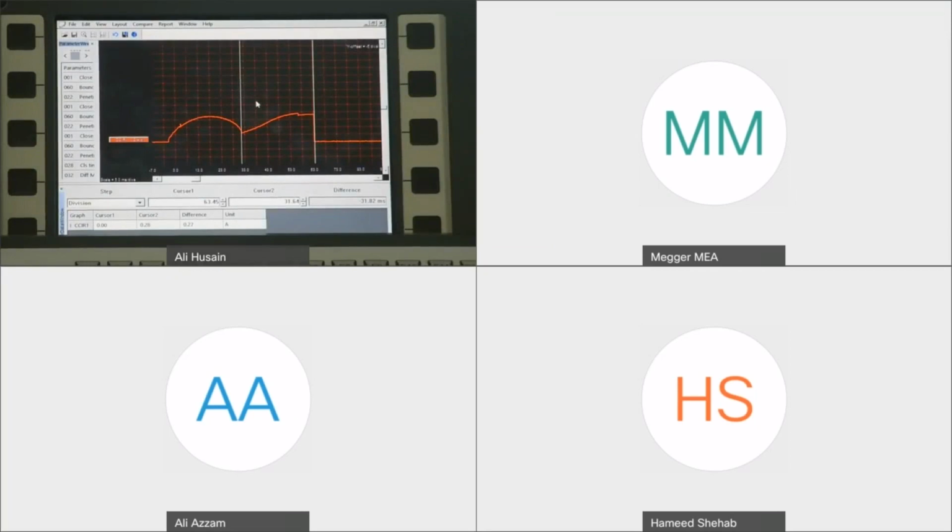So this, I would say, quick verification can really tell me whether I have a problem with my coil or whether I have a problem with my mechanism. So coil current test is one of the, I would say, basic tests that is recommended always to look at when you have any problem with timing test. If timing test is fine, then you don't really have to look at coil current that much.